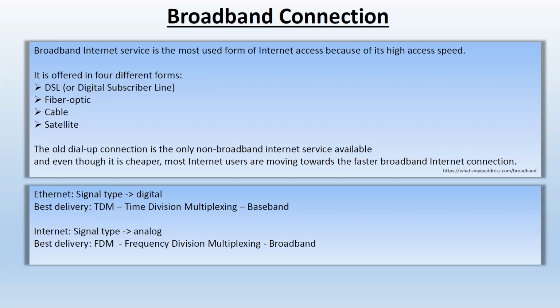But in order to test the line, you can plug in something called a hard loop, and a hard loop is just an Ethernet plug with the transmit pair and the receive pair coupled to each other. So the transmit pair goes right, loops up in about 2 inches of length or maybe half an inch, and goes right back into the receive line. So it's like a loop. And that could be used as a diagnostic tool to test the specifications of the line, right? So that's a hard loop.